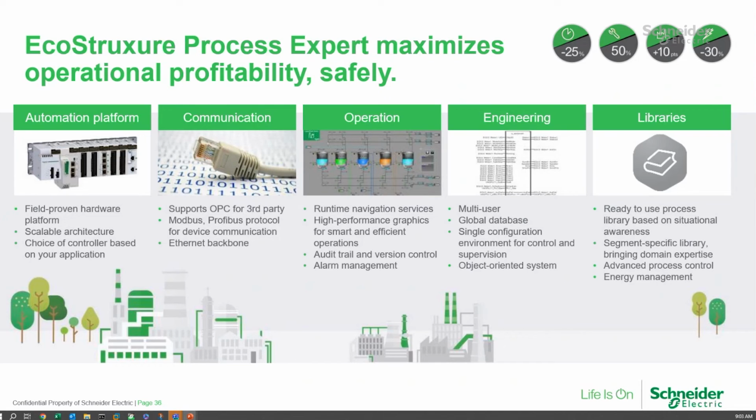From a communication standpoint, we're moving more and more towards OPC, and so we are certainly supporting that in connection to the Modicon controllers. But of course, our supervision systems support it for third-party use as well. And so all of the drivers that Plant SCADA offers and that system platform offers are available to us. And so we can talk to any third-party equipment from a supervision standpoint. And of course, if they can communicate in a standard open protocol that we use at the controller level, then we can communicate to those as well, including even at the M580, which now supports OPC UA client applications in the newest firmware.